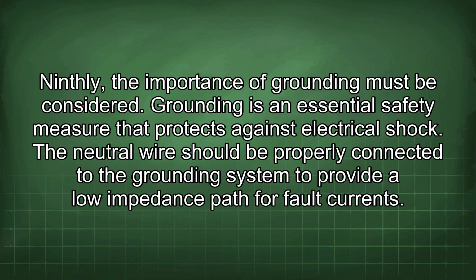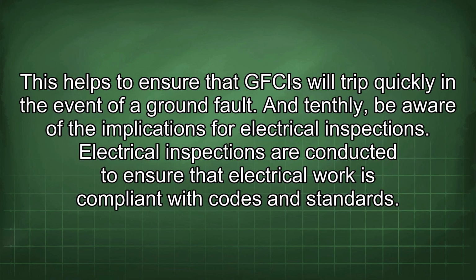Ninthly, the importance of grounding must be considered. Grounding is an essential safety measure that protects against electrical shock. The neutral wire should be properly connected to the grounding system to provide a low impedance path for fault currents. This helps to ensure that GFCIs will trip quickly in the event of a ground fault.